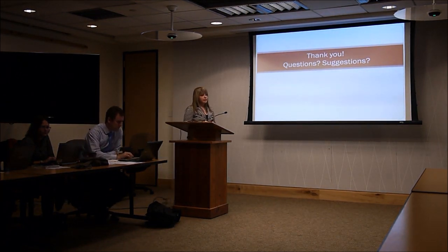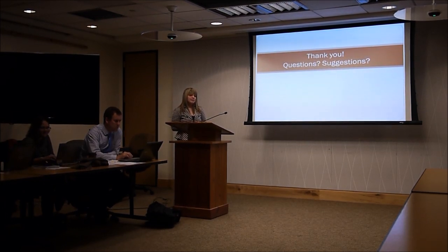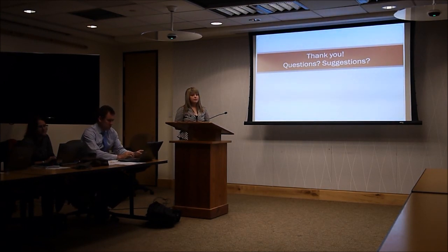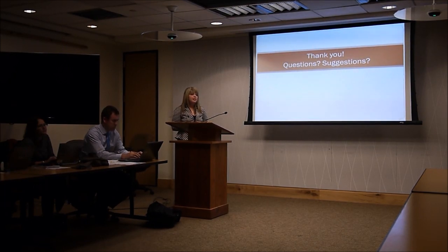Very interesting topic. I'm certainly here just to raise more problems, not solutions. But one suggestion is for you to look at the Curitiba case, because Curitiba has just introduced traffic signal priority for buses, but only for certain services, because we're talking about one-minute headways or even less, so you cannot provide it to everyone. So they did overtaking and also signal actuation.